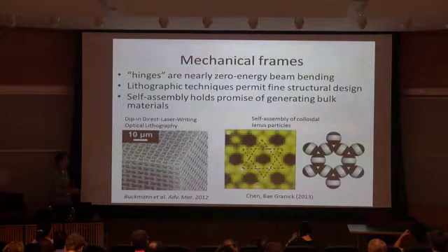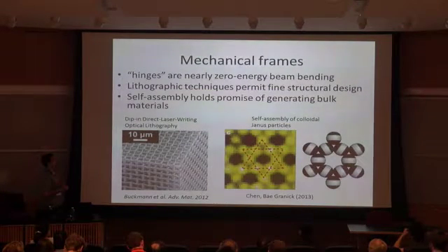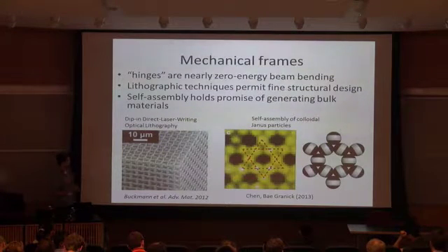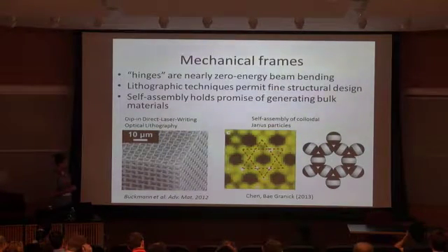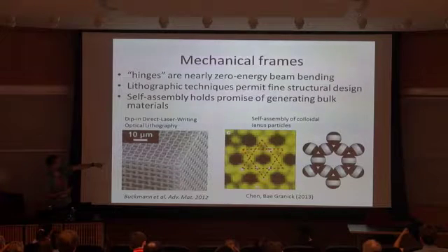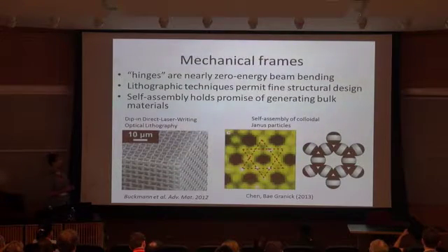And when we talk about going down to the microscale, there are a number of techniques that we can use to make mechanical metamaterials very small. We can do lithographic techniques to get this auxetic material, a material that has a negative Poisson's ratio. We can also do self-assembly of colloidal Janus particles. These particles have attractive patches that form bonds, but they also have repulsive bands in the middle, which leave open pores in between the bonds that give the particles free space to rotate into.